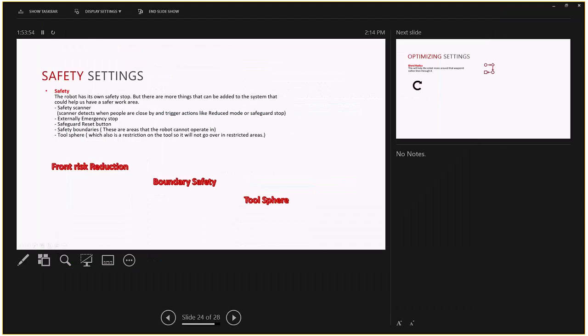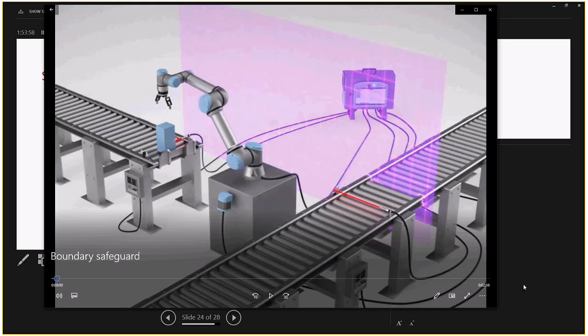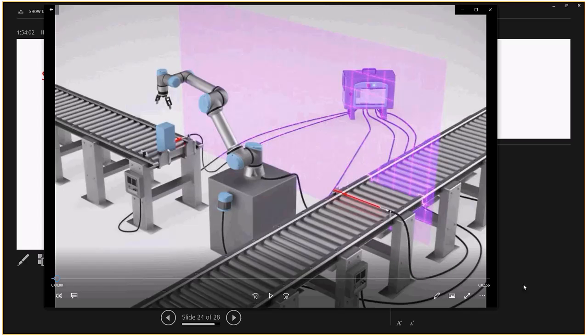Yeah, but if you press the reset stop button, then you will reset it. The robot will drop the box at the place where it was stopped. No, if you press the stop, and then after reset, it will release the grip and go to the... Yes, it will reset the whole thing. The whole robot will go to position 0. That's what it will do.